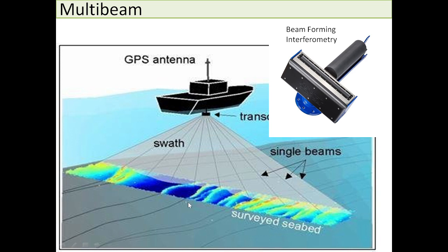So you are able to see the complete width, but this is on the surface of the sediment layer. So this is very useful to have the live storage capacity estimated, and you cover a wider area. Normally with our practical equipment, we have seen about 100 to 200 meters of swath being covered with such technology. So you can plan your survey grid lines of about 100 meters or 200 meters, and in between the data is logged automatically. In case it is a single beam, you will be getting only this. All these are missed. So that's the point here.